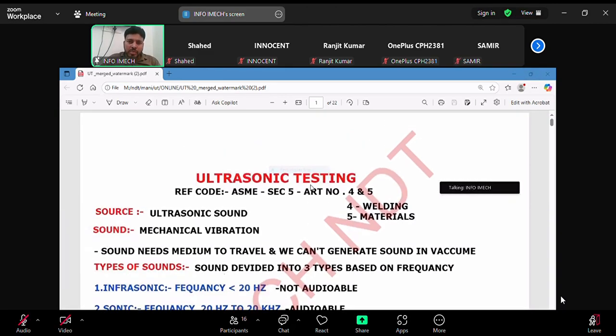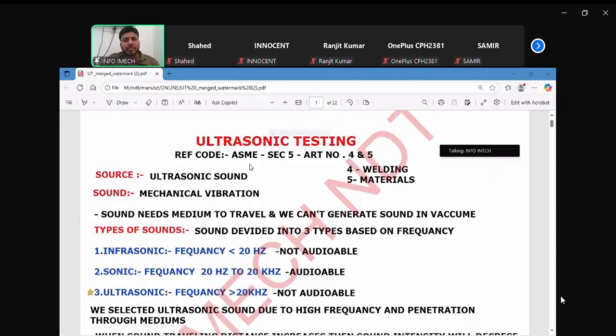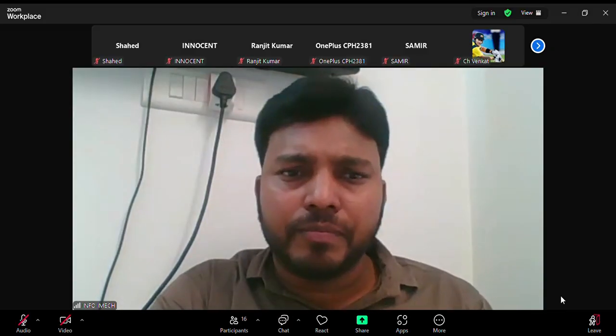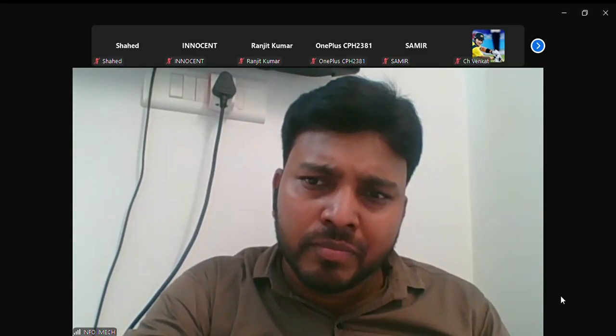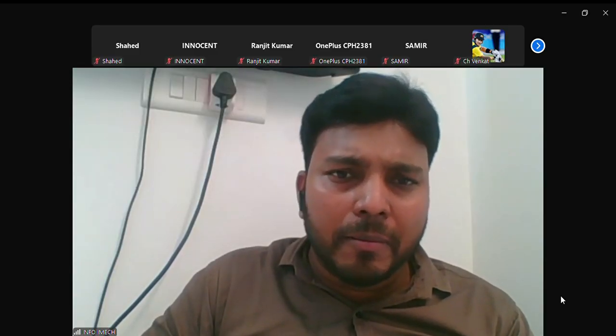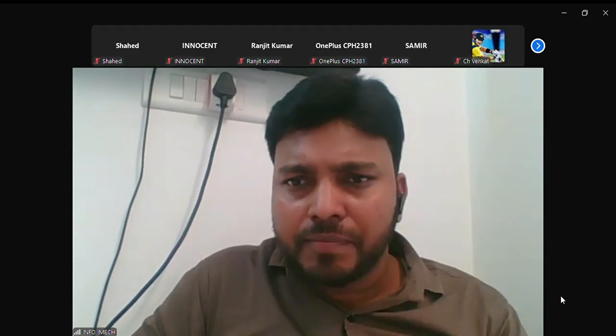So, American Society of Mechanical Engineers, Section 5, NDT: Article 4 for welds, Article 5 for non-welds. The source in ultrasonic testing is ultrasonic sound. So first of all, sound. What is sound? If someone asks you a question, what is sound? Sound is a mechanical vibration.